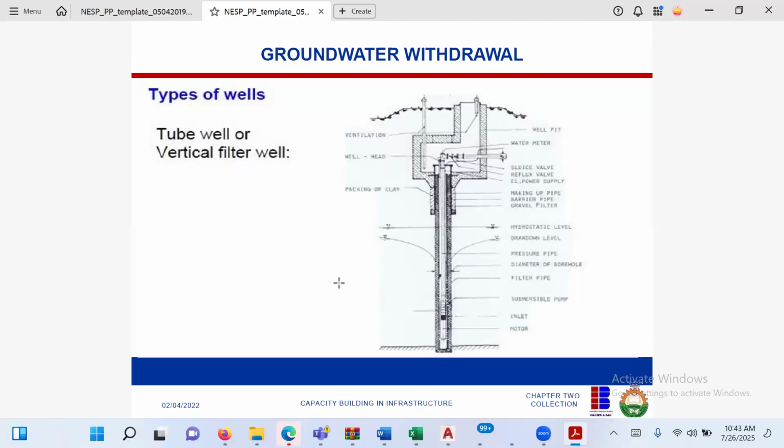These pressure pipes are very key, gentlemen. Please, the pressure pipe of a borehole starting from 60 meters should be minimum of 10 bars. As you are going down, you should be increasing the pressure of the pipe. This is what kills a lot of boreholes. Ideally, you should go for 12 or 14 bars, because as you are going deep in the ground, you need a strong pipe, a pipe that can withstand that level of pressure.